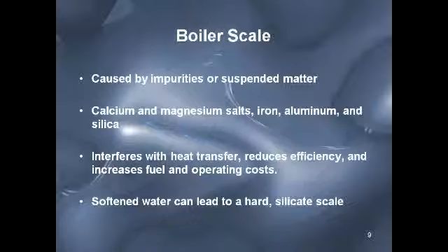To help you understand how much a boiler's efficiency is affected by scale formation, note that just a 1/16 inch deposit of scale on the water side of the boiler's heat transfer surface relates to a 15% energy loss, and a 1/4 inch thickness of scale results in an almost 40% energy loss.